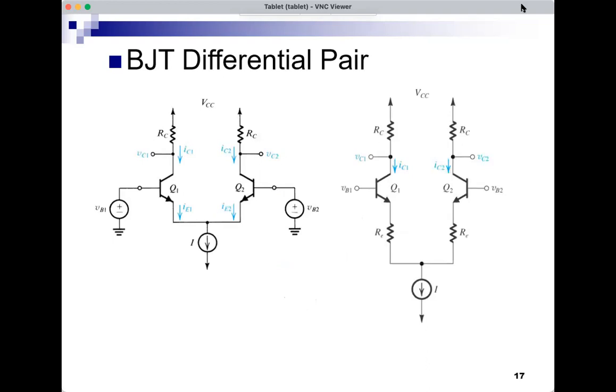And in many cases, actually, you may see that there is a resistor, RE, that is inserted between the emitter or the two emitters and the common node here. This RE has two purposes. The first is that it will increase the input resistance. And we will see how on the coming slide. So it helps in increasing the input resistance of the amplifier.